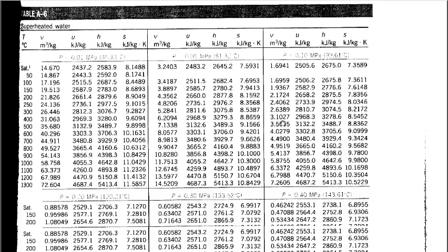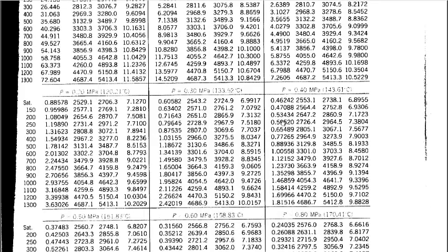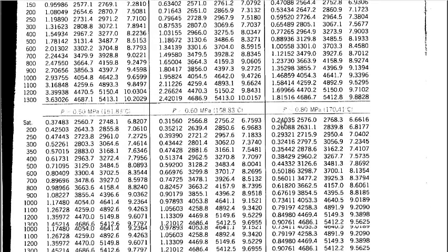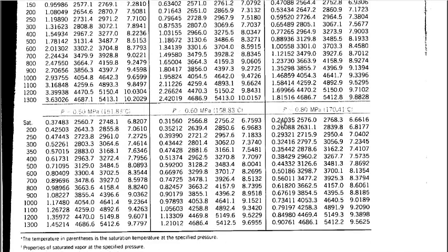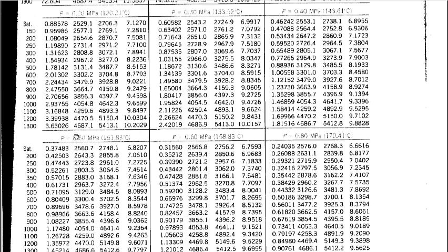And if we just keep on doing that, eventually we'll find out that there's going to come a point where we cannot have water at 200 degrees Celsius. If we get to such a high pressure where even at that very high pressure water doesn't vaporize yet, it will no longer appear as a temperature on the left-hand side of table A6.